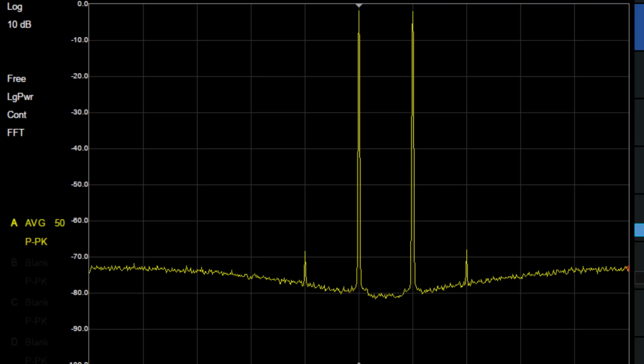The next question, what signals are used to conduct a two-tone test? What a two-tone test really is, is inputting two tones of equal power that are not harmonically related. So two different frequencies, equal power, into a single sideband transmission. So the answer is two non-harmonically related audio signals.